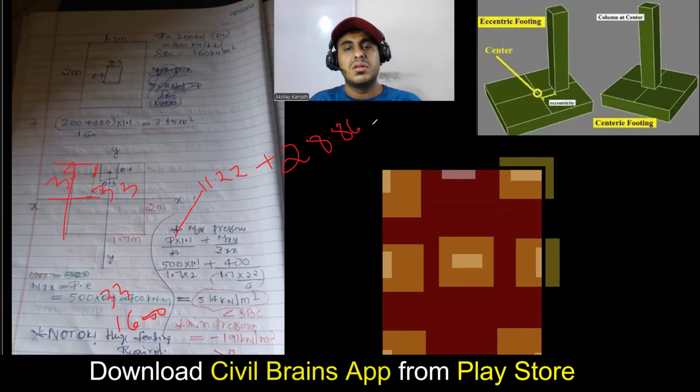28.86. This is also fine, no? So add it: 28.86 plus 11.22 is 40. So 40 is less than 160. I'm okay. This is satisfied. Your maximum pressure condition is satisfied.